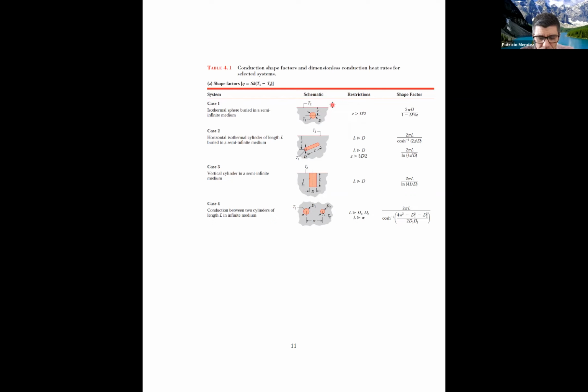True. This formula accounts for the thermal resistance of the flesh. The flesh has no heat generation, at least in this simplified model we're talking about. So this is the flesh with no heat generation in steady state, and the pellet has some amount of heat generation, but it doesn't matter, it's just an amount of heat that is imposed. And that will result in a delta T that should not be excessive. Otherwise, instead of giving a patient radiation, you're just burning them.